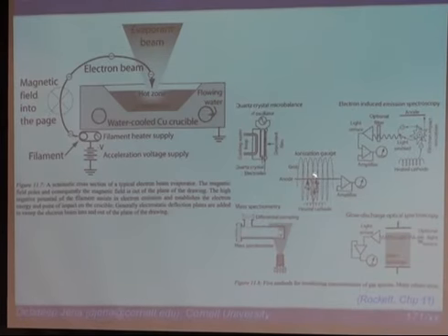The electrons deposit on one grid and the ion deposits on the other. Because now you have an extra electron and a positive charge, there's a blip in current, and by how much the current changes, you amplify it and measure how many atoms are going through. That's called an ionization gauge for obvious reasons. It's ionizing the atoms and measuring how many atoms are inside that region.